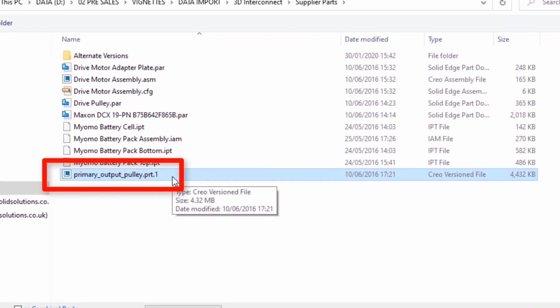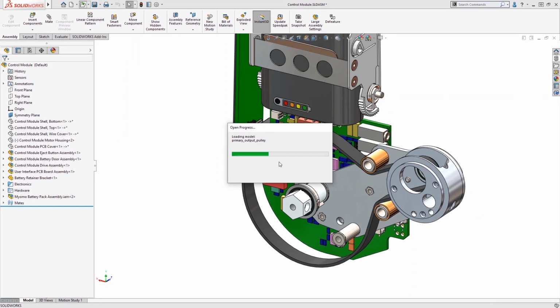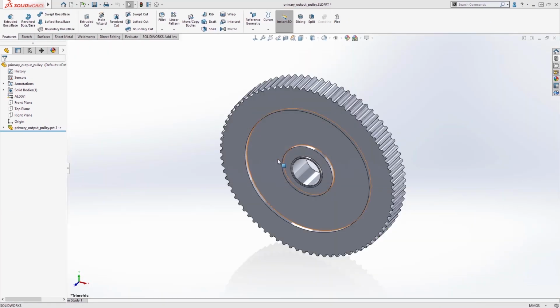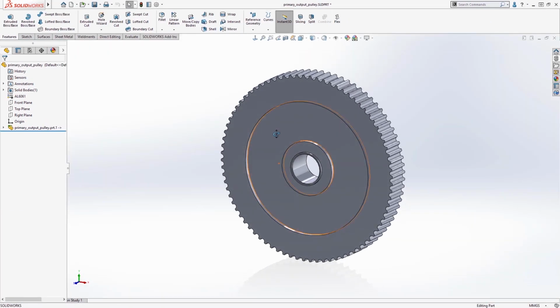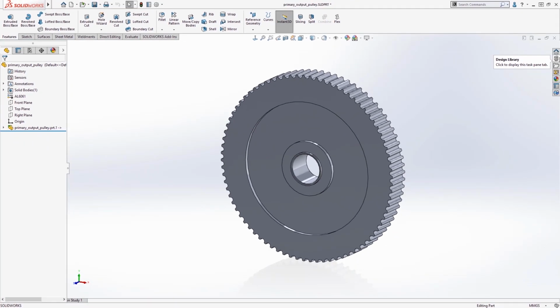This is how PTC handles revision changes and will come into play in a moment. Let's just open the file. Notice this time that the top level is an actual SOLIDWORKS part file. However, instead of a traditional imported geometry feature, we get a base or derived part. It is the same unique icon as before, letting us know that it's referencing the native CAD data.